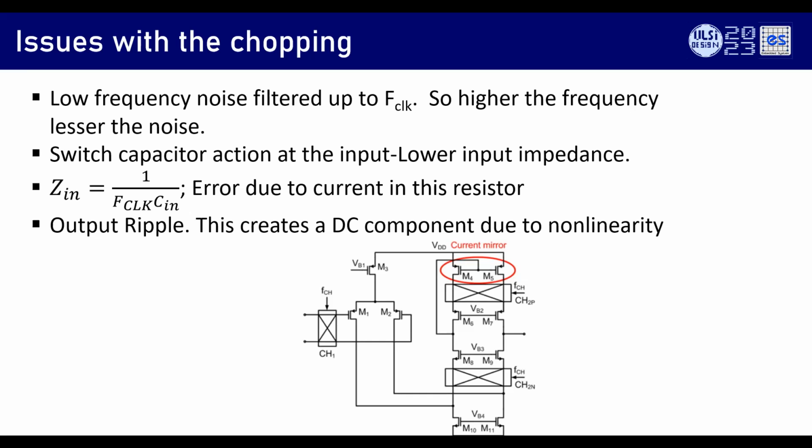For example, if you have a resistor at the virtual node of the operational amplifier, it lowers the virtual node impedance of the operational amplifier, and hence the amplification factor of the offset and flicker noise becomes higher. We should not lower the virtual node impedance of an operational amplifier. If you do chopping, you will indirectly. How much depends, but you will do something to that. But this is only a note.